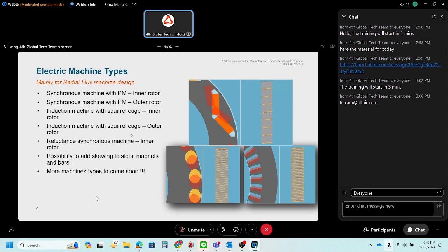So, yeah, the macro also allows you to perform some specific analysis, like cogging torque, like back EMF, like single working point and efficiency map, as well as thermal analysis. So, yeah, don't hesitate to ask to test it, or to ask if you need more information.